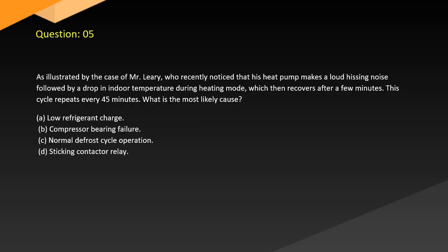Question 5. A customer recently noticed that his heat pump makes a loud hissing noise followed by a drop in indoor temperature during heating mode, which then recovers after a few minutes. This cycle repeats every 45 minutes. What is the most likely cause? A. Low refrigerant charge. B. Compressor bearing failure. C. Normal defrost cycle operation. D. Sticking contactor relay.